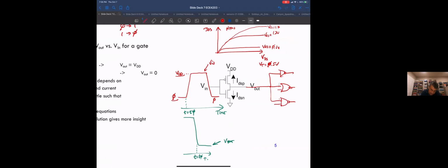But this is very critical. We've mentioned a couple of times, all these inputs are purely capacitive. They're not going to be outputting any current back into this NMOS. So all this NMOS is doing is discharging this total capacitance, so it's going to go all the way to zero. The model for this load is purely capacitive.